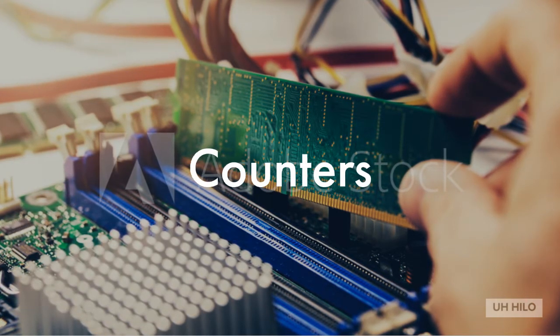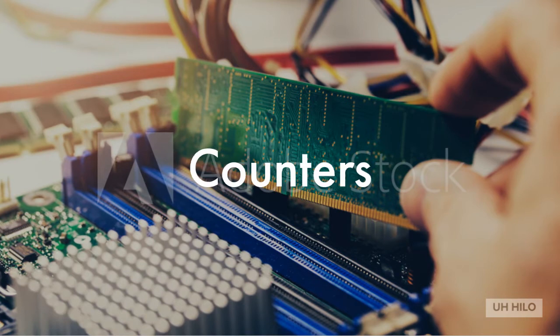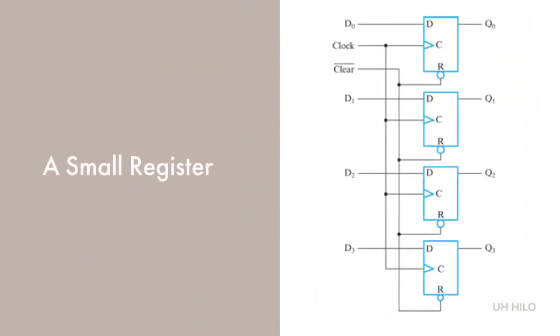Registers are useful for storing and manipulating information. Counters are employed in circuits that sequence and control operations in a digital system. The simplest register is one that consists only of flip-flops without external gates. Here we have a register constructed from 4 D-type flip-flops.